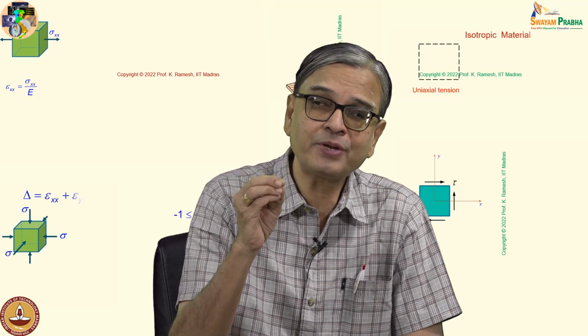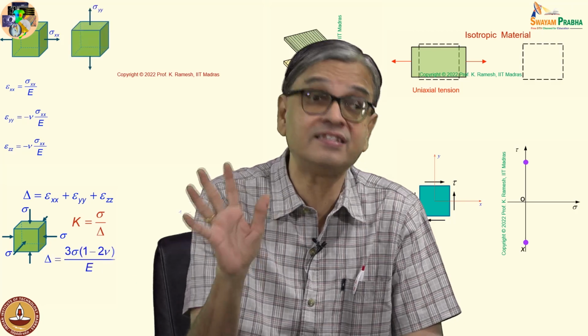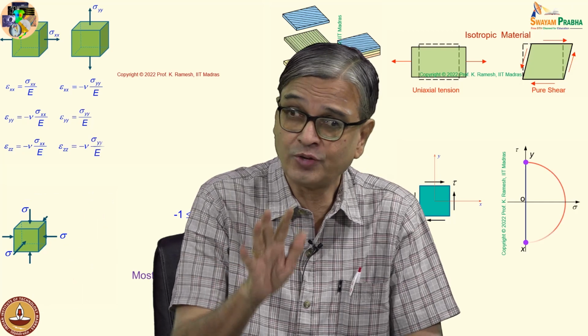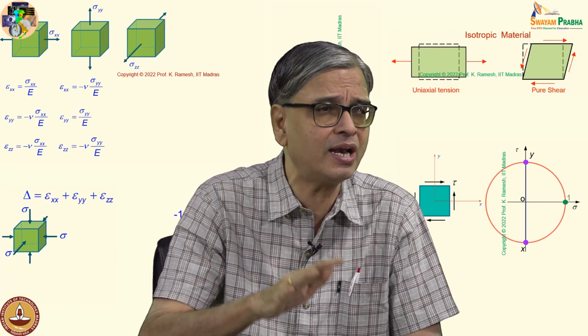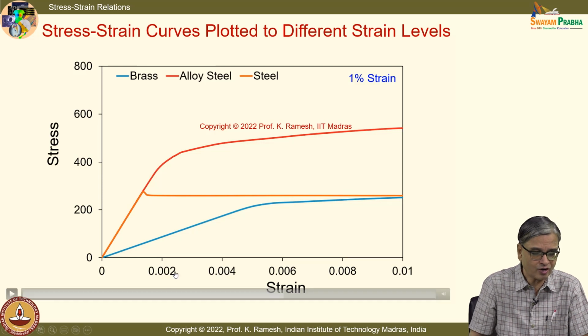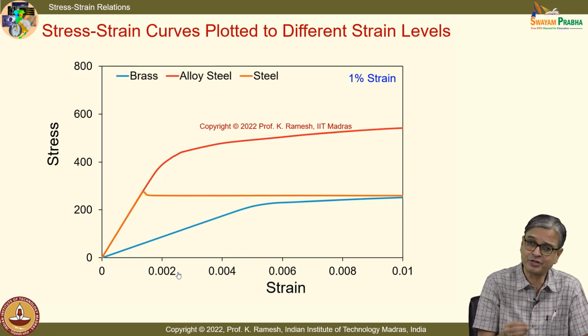So, what you will have to appreciate is at 0.2% strain the material yields. It's a very, very important knowledge. Never forget this. So, we operate at a very, very small level of deformation. I can say it as 0.2% strain, or I can call it as 0.002. I can also say 2000 micro strain. So, whichever way it is mentioned, you should be able to appreciate this.